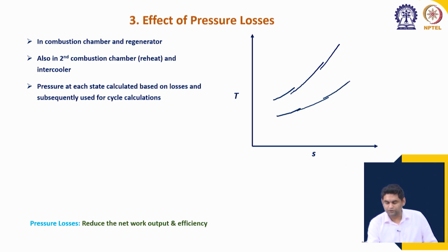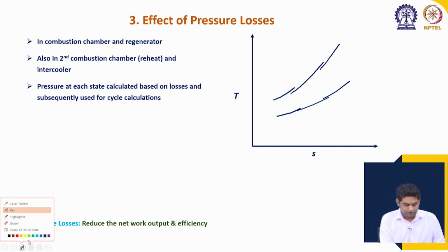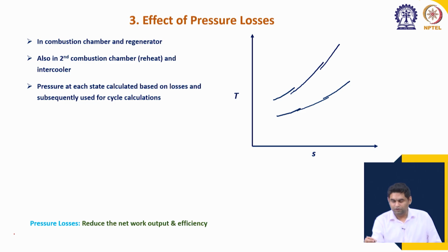And we will draw some more constant pressure lines and I will explain what we are doing. So, now for the compression process we are going from 1 to 2, right. So, this is 1, this is 2s. So, instead of 2s we will go to slightly higher entropy which is, let us say, 2.